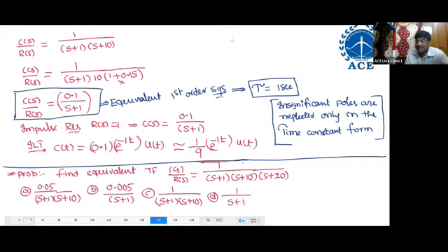Why? Because these two are insignificant poles. This time constant is 1 second, this one is 0.1 second, and here 0.05 seconds. So these two are insignificant. Comparison is always with the dominant pole only. 10 times less, 20 times less. Both are neglected. So what can I write?